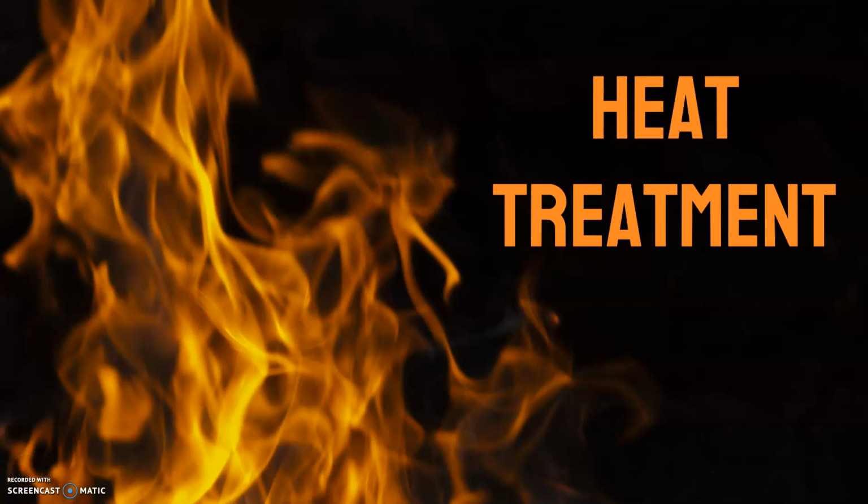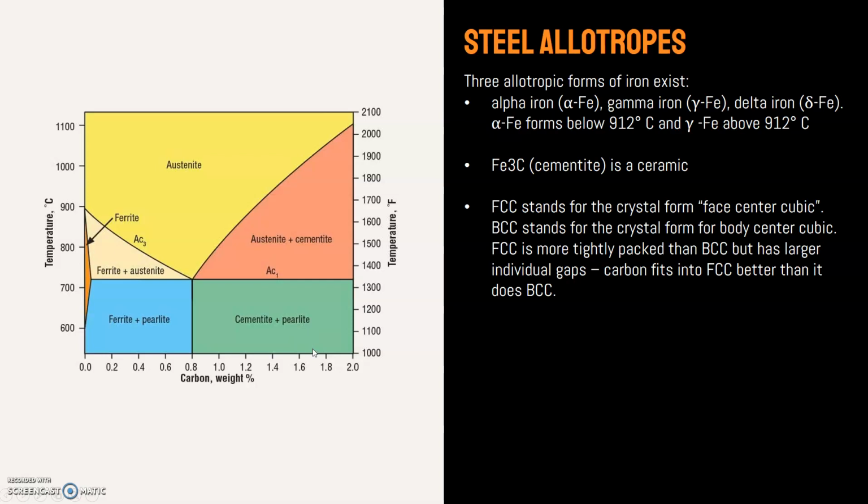So now we're going to talk about heat treating. There are different methods of heat treating, or causing materials to change their properties without changing their chemical composition. In steel, there are three different forms of iron. We refer to them as allotropes: the alpha, the gamma, and the delta.